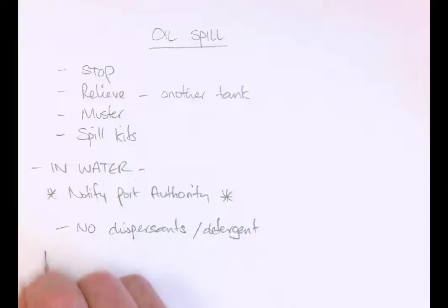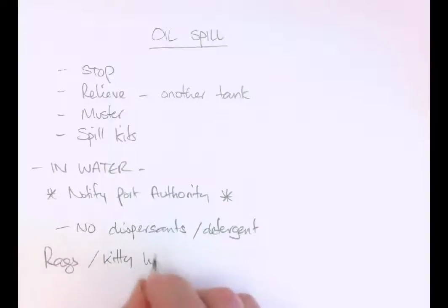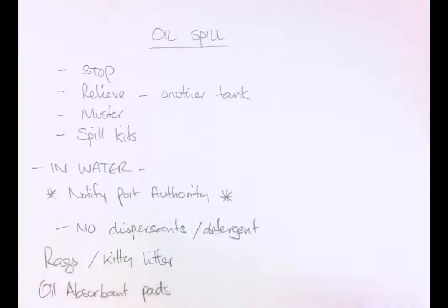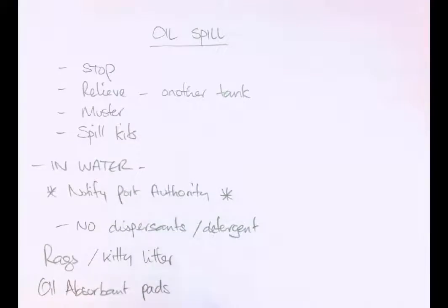All right, and then it's a matter of using rags or kitty litter if it's on deck, oil absorbent material to clean up the spill, and the oil absorbent pads. These are great. You can even put them in the water if there is a spill in the water, because they absorb oil and not water. That's the way they're designed.